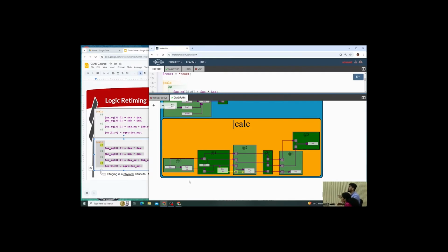What will be there before X3 to 1? Nothing. They just don't exist. What is the exact meaning of 4.6? That means 4 is the 0th stage of the pipeline. So the numbering is all relative. How you choose to number the pipeline, where you choose to start the numbering, is arbitrary. That's up to you. If there's some association with another pipeline, you might align the numbering, but it's the relative difference that matters. So you could take any TL-Verilog logic and renumber an entire pipeline by shifting the number scale, and that would preserve the functionality of the design.